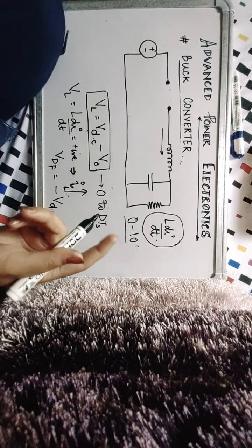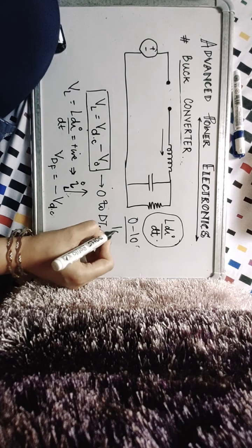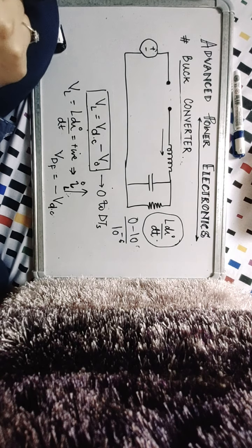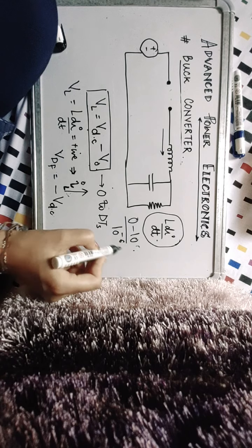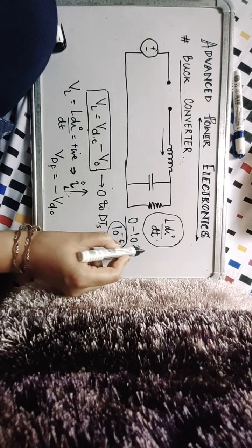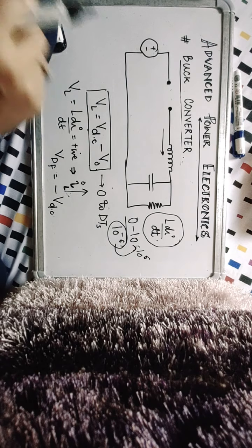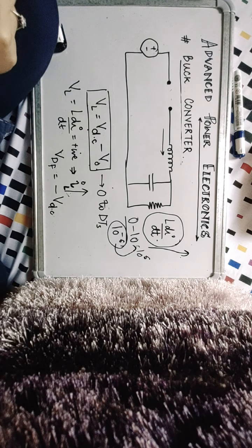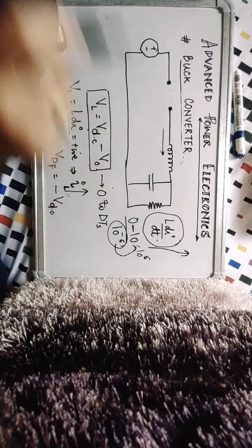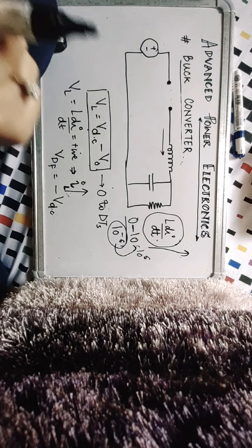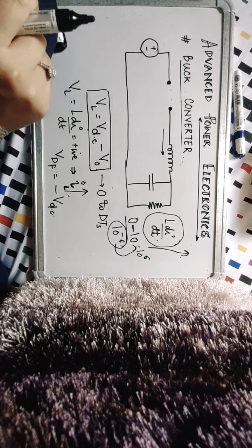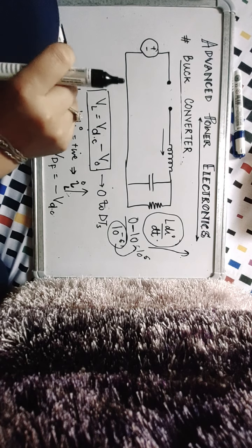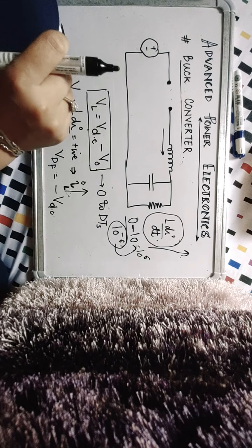So if the device turn-off time is maybe of the order of 10 raised to the minus 6, 1 microsecond, then a very high magnitude, it becomes 10 raised to the 6 here, a very high magnitude L di/dt kick with a negative sign, 0 minus 10, a negative direction, high magnitude inductive kick is induced.